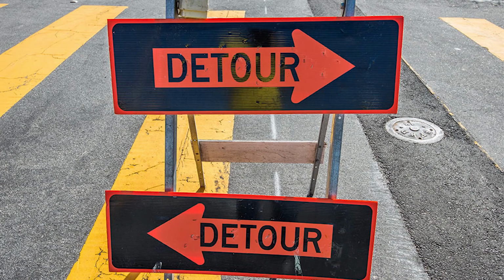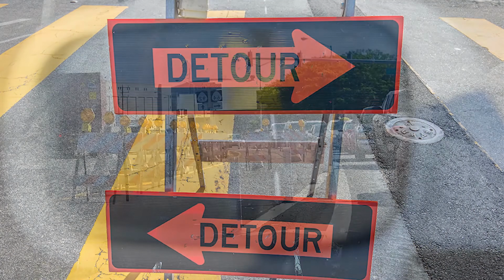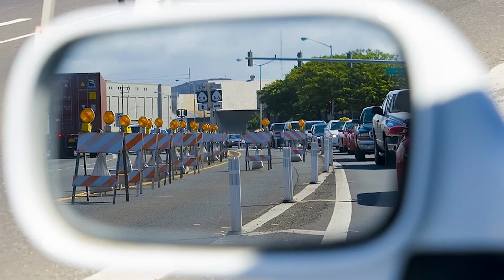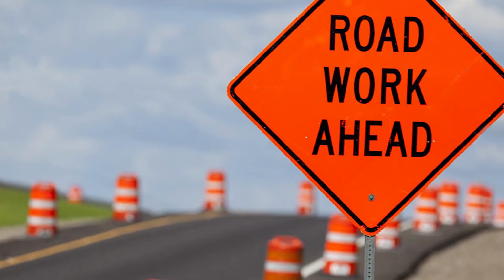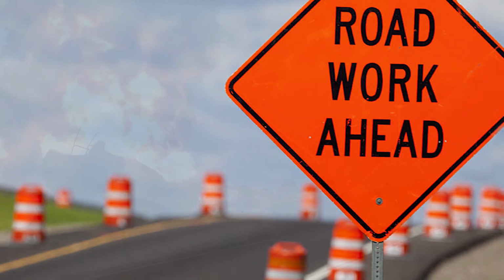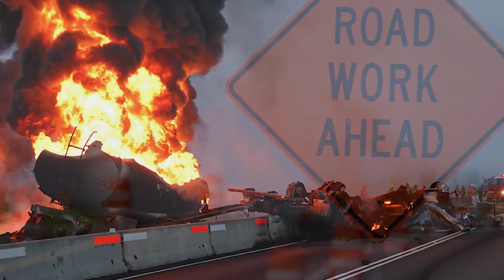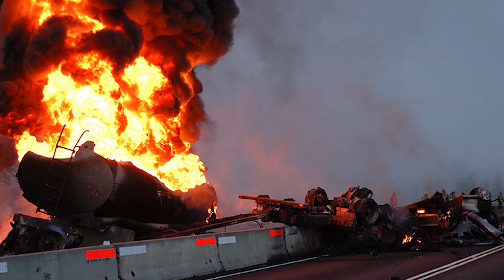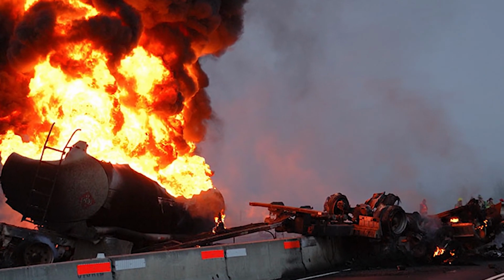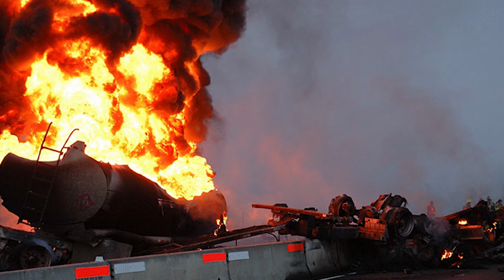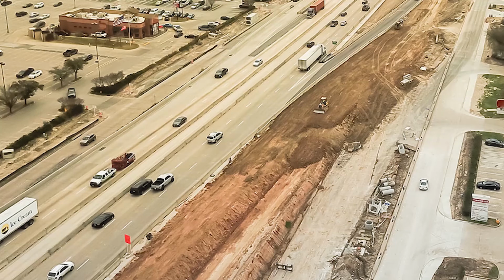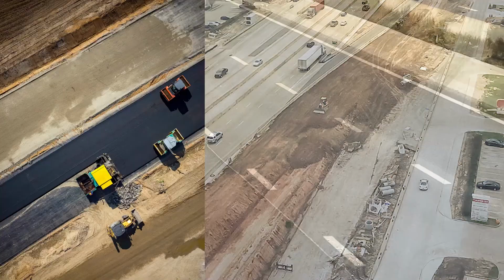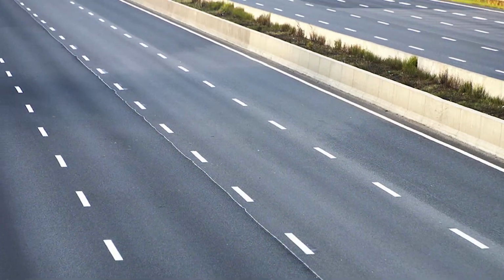Some road user cost factors that lead into that cost to the traveling public are detours that add to travel time, reduced roadway capacity that slows travel speed and increases travel time, delay in opening of a new or improved facility that prevents users from gaining travel time benefits, additional costs such as operating costs for the vehicle and accident costs due to the construction being there or some effect that wouldn't have been there without the construction. And then road conditions, which could be comparing the before and after construction or the during and after construction cost.